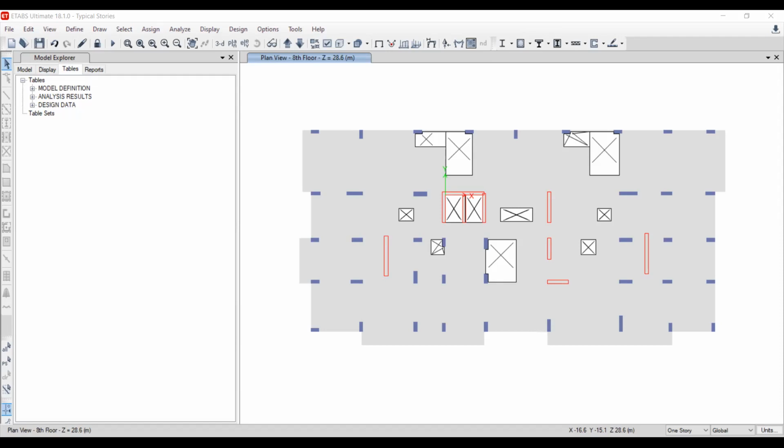So this slab will be the same as in ETABS. Right click, left node, you see the live load and the dead load, 3.5 by 1.2, which is the same as in ETABS. You can go to 3D also, you can see this one. Okay, XY. So now we need to define, we have the load combination here, combination 17. We can define the load cases.